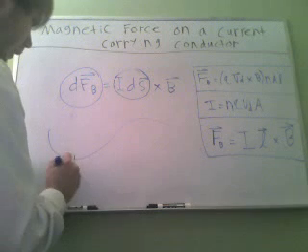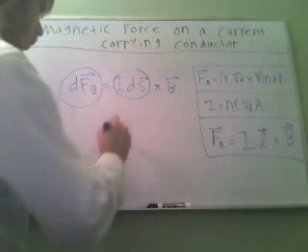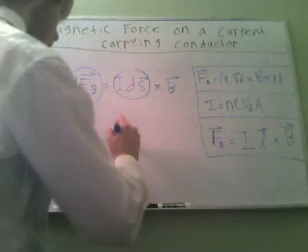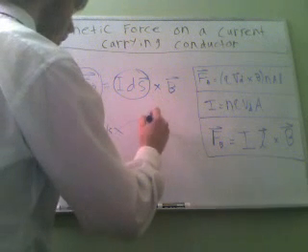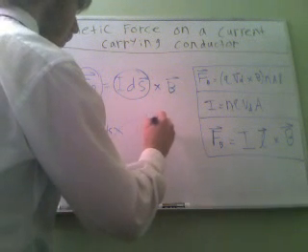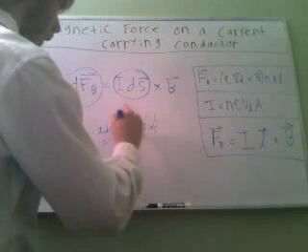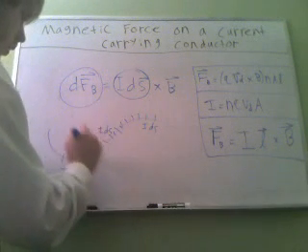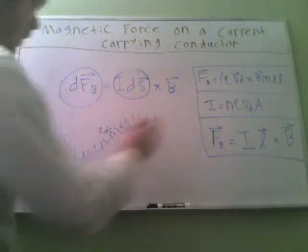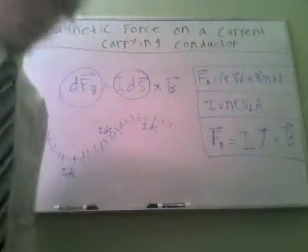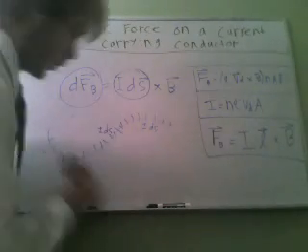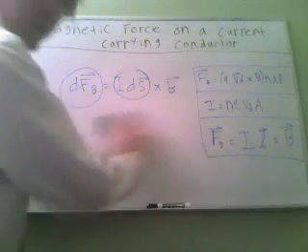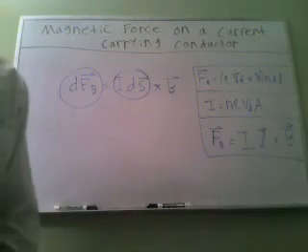There is an I dS. Well, here's the straight section. This is the I dS. Here's another. It's the I dS. Well, if we just keep doing that until we break it into small blocks, we'll eventually have all these little pieces that we can add up. That's essentially what we're doing here. We're using calculus to add up all these small sections so we can know the total current, so we can figure out the total force.